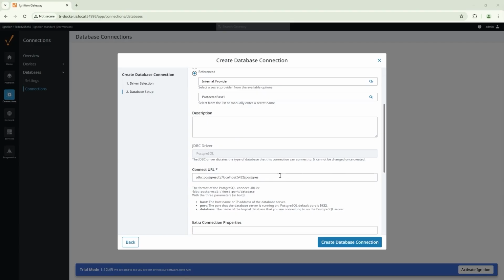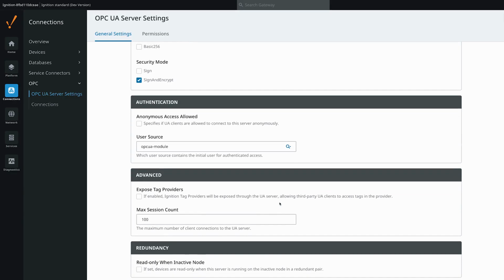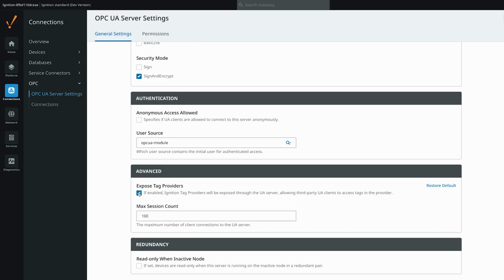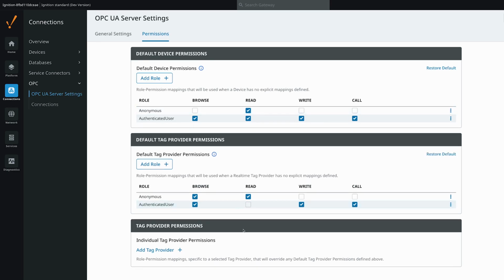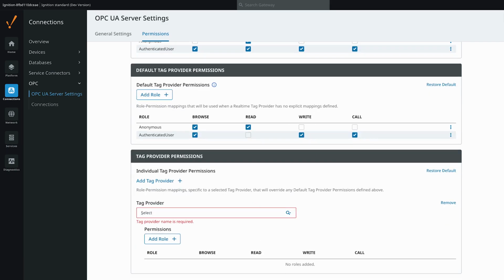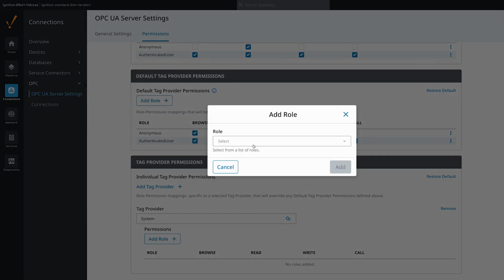These security improvements also extend to how your data moves through your system. Ignition 8.3 boasts new serialization that improves the throughput of data for reliable, secure communication between gateways. The new OPC UA roles feature lets you get granular, picking and choosing which users have access to specific tags, while the latest OPC UA specification provides greater integration and access control for device and exposed tag access for third-party OPC UA clients.